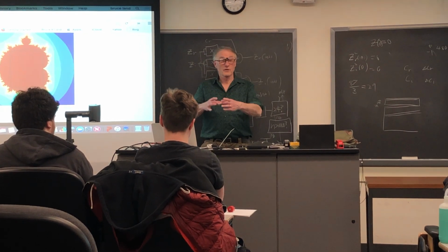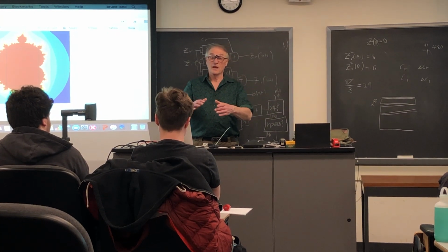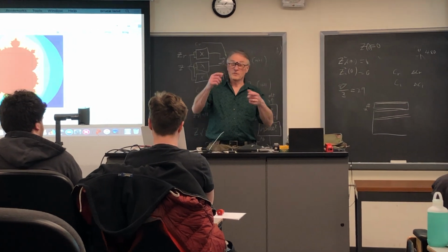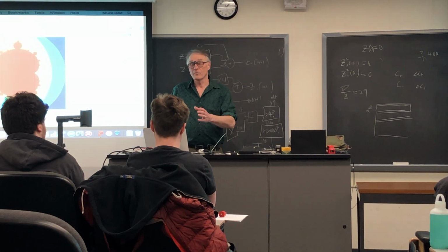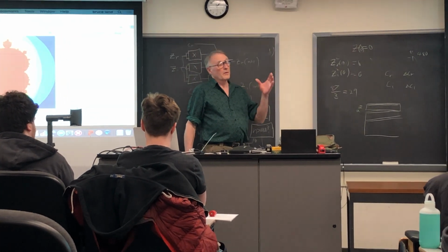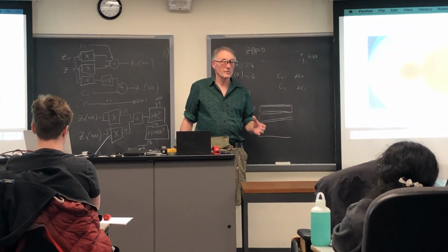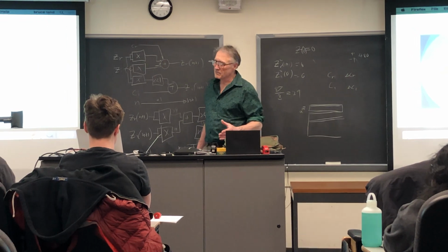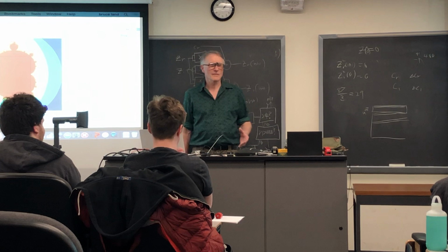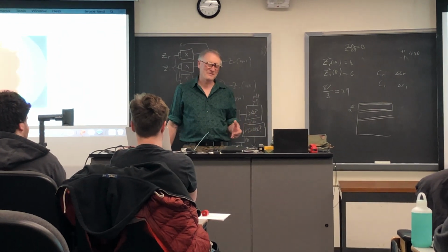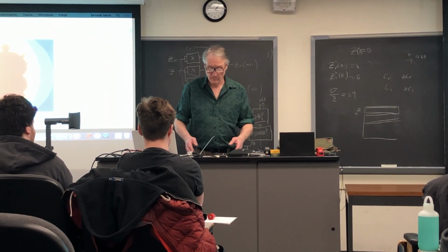They built a daughter board that plugged into the expansion connector of the FPGA. They took the output from that, deduced the region where the ball was appearing, calculated the velocity of the ball from the color of the ball, and made a closed loop, optimized PID controller. 3 guys, didn't sleep for 5 weeks. I don't recommend that. But they got it to run.